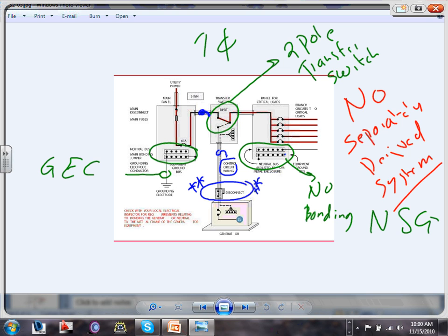And I want to bring to your attention, guys, an overcurrent protection device right in here. Why overcurrent protection device? Because you want to protect the feeders. Why disconnect? Isolate completely the system. Could the disconnect and the circuit breaker be one? No problem. If you can lock this disconnect in the open position, no problem. Any question, guys, about that?